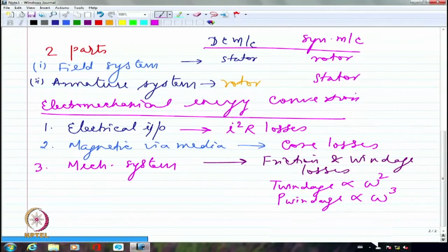So we are essentially looking at two components. One is like a static friction. In fact, friction itself we will be looking at different things. Viscous friction will be proportional to omega. Static friction will not be dependent upon omega at all. The static friction is the initial frictional component which will be required to give the initial momentum. And the third component is windage. So you will have essentially three components if you want to really do the hair splitting completely for all the frictional quantities. Right? Okay.